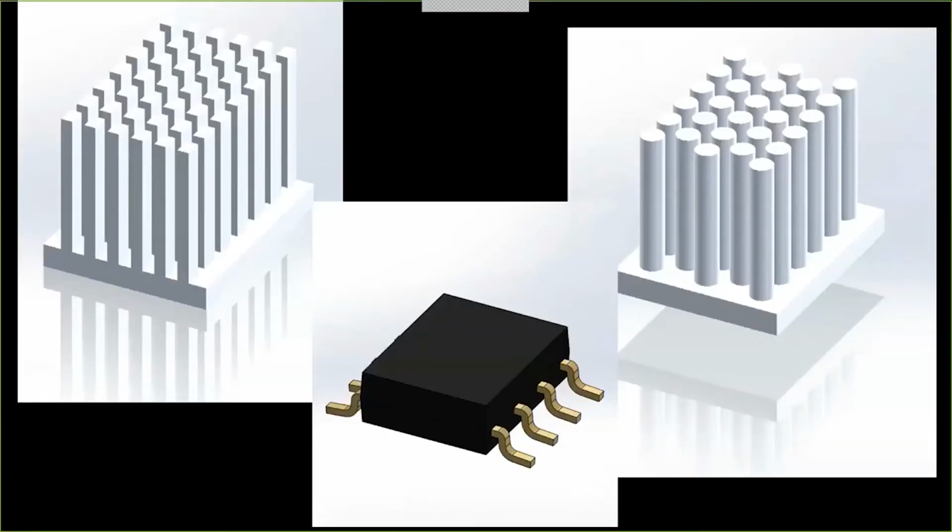So my next step was, well, let's look at adding a heat sink. Can we get some of that heat out of the constant current source? And there's a couple different heat sinks available. We've got a pin heat sink, which is generally a far more expensive way of doing it. You could possibly do metal injection molding or die casting if you were using zinc or aluminum.